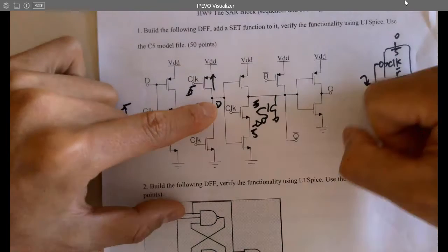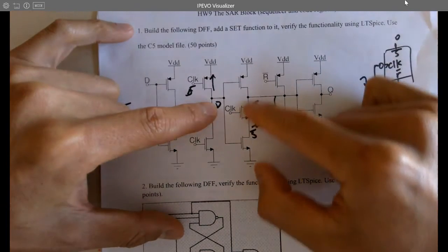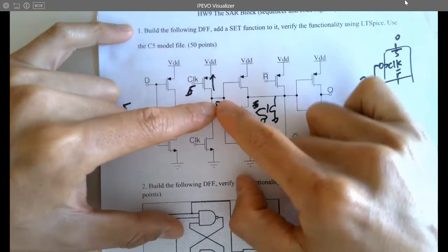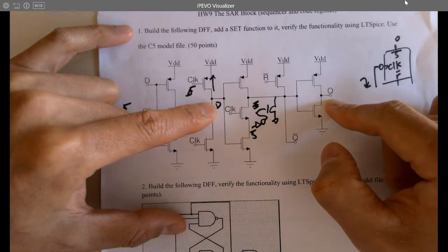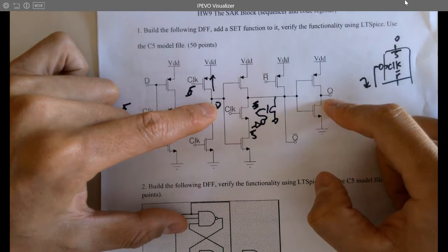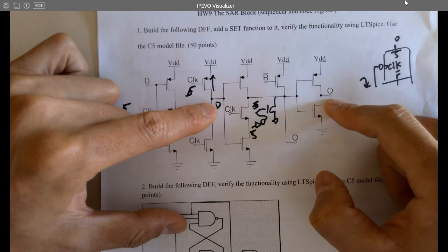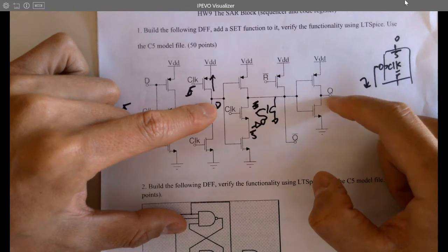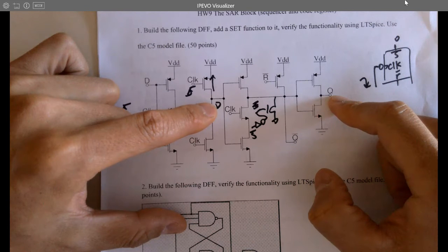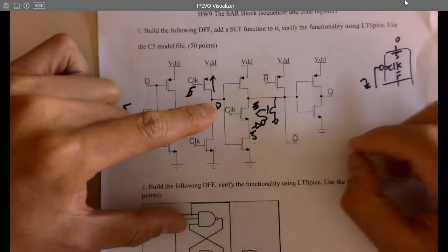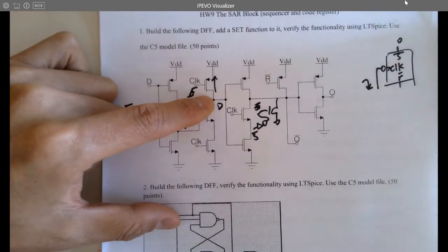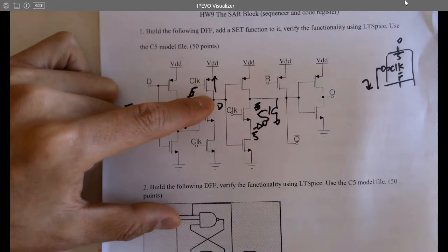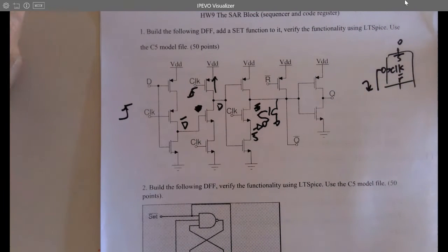Okay. At the rising edge, this becomes a wire, so this becomes an inverter. So D will be inverted once and twice. So D bar and D. So D will be transferred to Q eventually at the rising edge. Make sense? So it is a D flip-flop. You'll figure out after you do it yourself. You'll figure out you do need something here to control it. Multiple rising edges? No, just one rising edge. We're just talking about one rising edge.